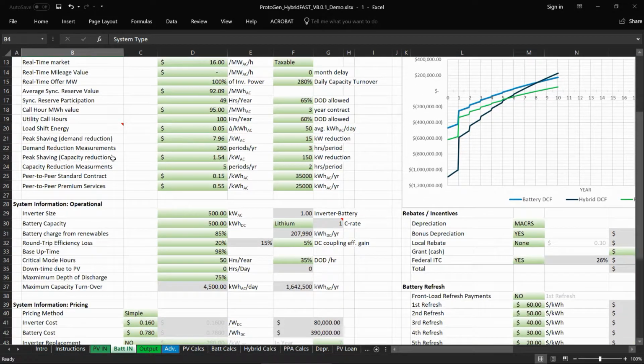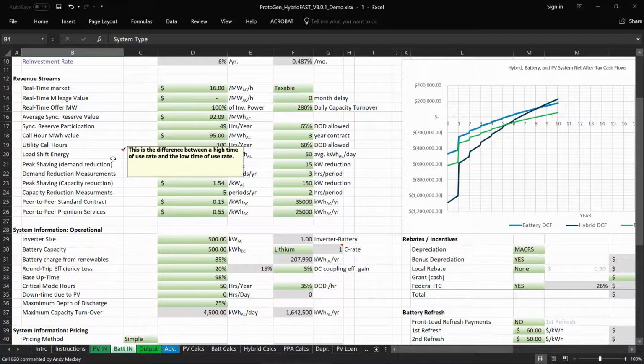The next big section that's unique for the battery system is the revenue streams. We currently have a multitude of potential revenue streams available, but for this analysis and in our first pass, let's simplify it a little bit. Let's assume that they are primarily focused on the real-time market, which in Pennsylvania for us is the Reg D ancillary services market, sometimes commonly referred to as fast frequency response.